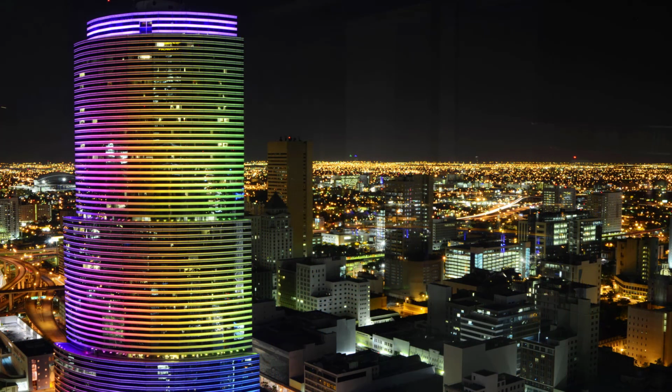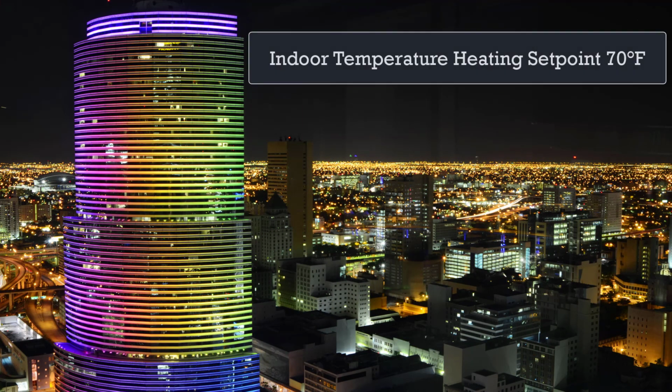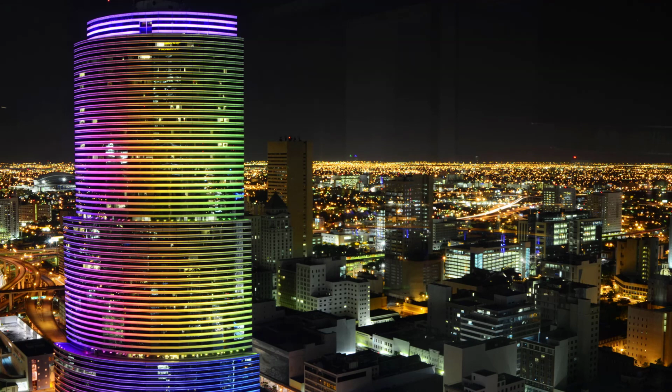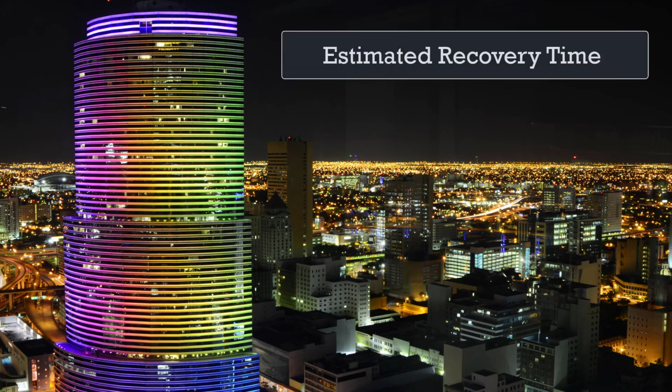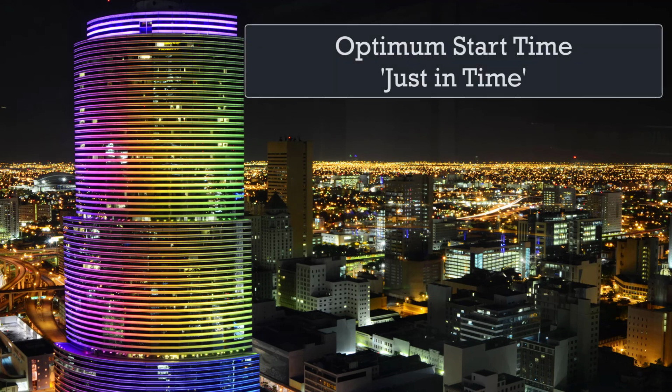With our BAS program setting the building occupancy time of 8 a.m., indoor temperature heating set point of 70 degrees Fahrenheit, and indoor temperature cooling set point of 74 degrees Fahrenheit, the next step is to program our BAS Optimum Start simulation based on what is referred to as estimated recovery time, then observing and readjusting as necessary. By definition, optimum start time is the latest time the HVAC system should start so that building indoor temperatures reach the desired set point at the occupancy begin time.